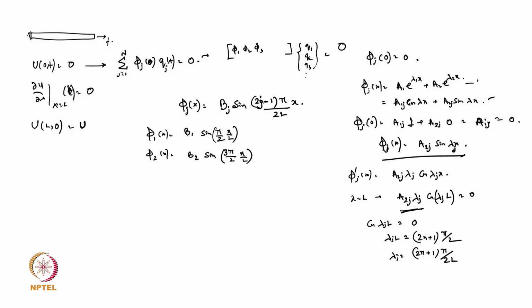Now here, if you try to recall, where is the difference with the finite element? Shape function, exactly. In finite element, we are not calculating the shape function from the boundary conditions. We just pre-assume the shape functions, that this is a linear variation.